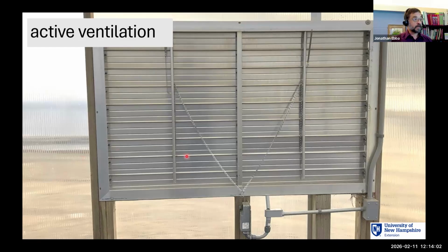And one of the big things is where you put this inlet louver, and I've seen them on small houses that are just passive. This particular one has a motor, so when the exhaust fan comes on, this motor opens these louvers. I have seen these, and I've installed them myself, where they're just passive and flapping in the breeze, and on a small enough house, the exhaust can create enough static pressure that it'll open up those intake louvers by itself.